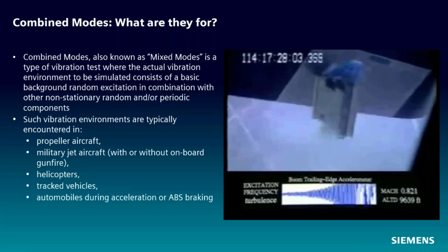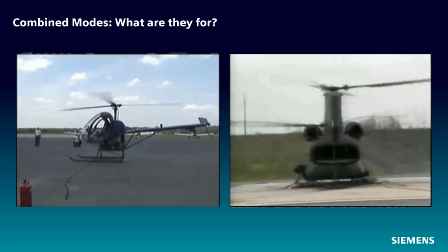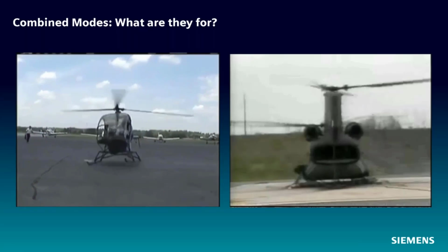You ever hit the brakes really hard in your car and you get that nice foot massage? That is the anti-lock brake feature, pulsing those brake pads so the brakes don't lock up, and that gives you a sinusoidal vibration on top of whatever random vibration you're getting as you go down the road.